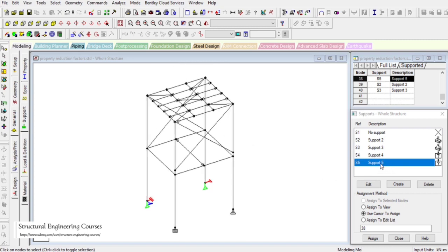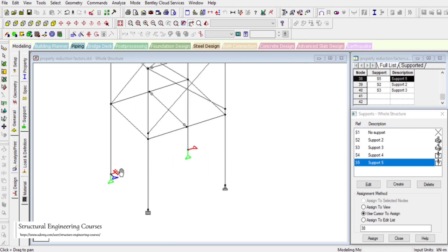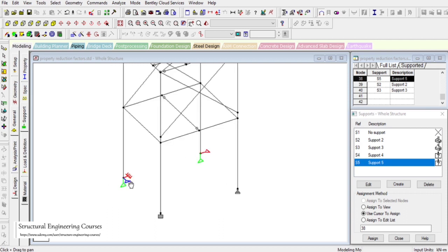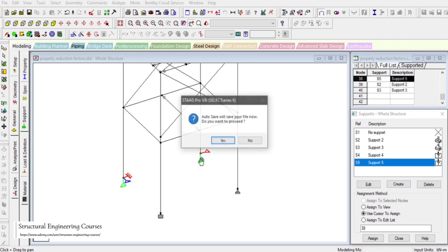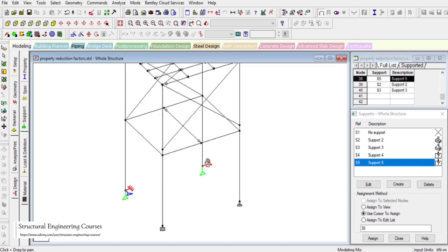So in fixed but foundation, the software clearly shows what exactly it is doing. We have added various types of foundations. This is a fixed foundation: all three Fx, Fy, Fz and Mx, My, Mz will show a value here. Only Fx, Fy, Fz will show a value here; Mx, My, Mz shall be 0. Only Mx shall show a value here, and My and Mz shall be 0. And for this, Mx, My, Mz shall be 0, as well as Fz shall also be 0.